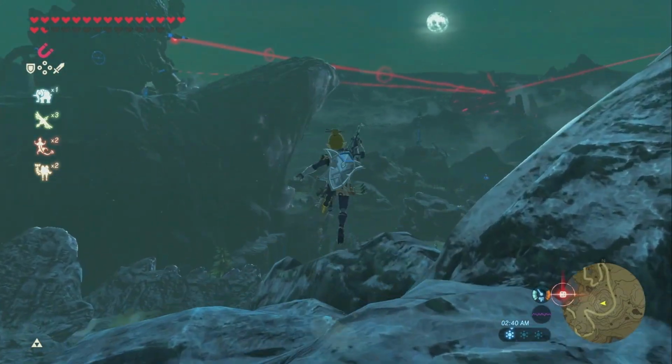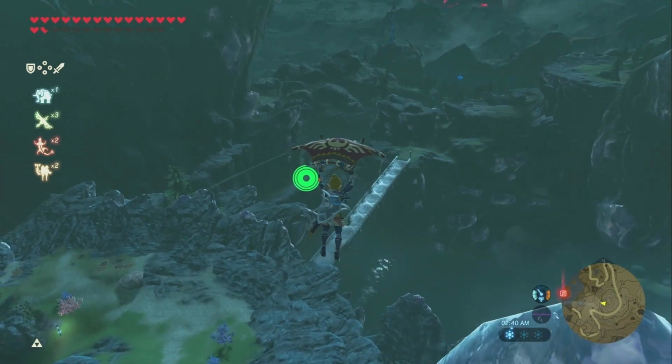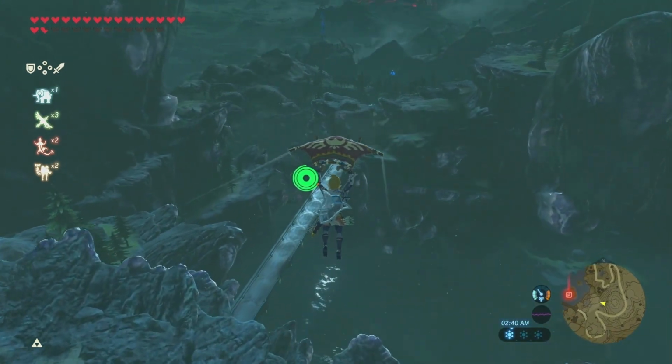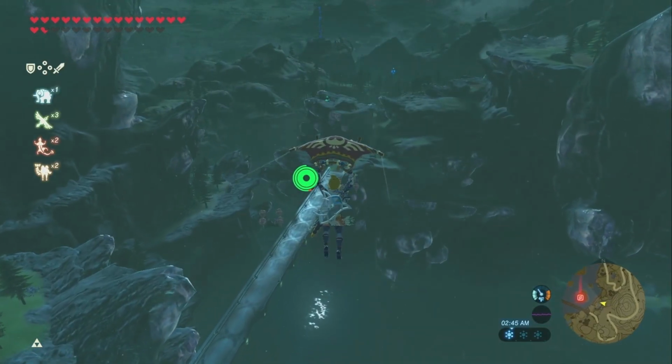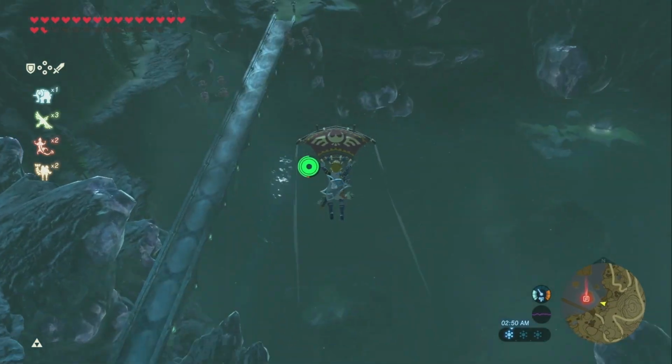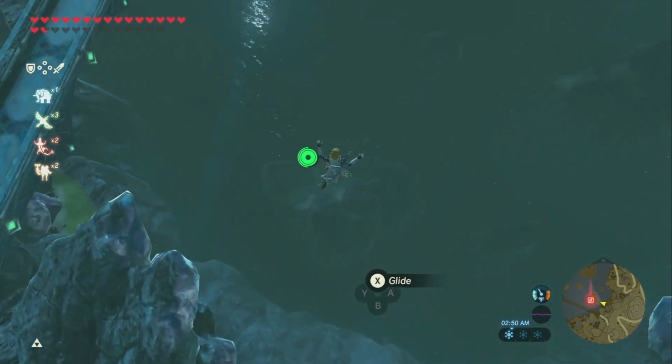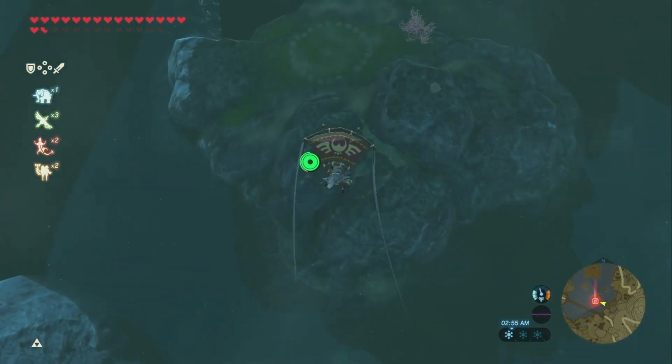Get rid of the chimney. A common approach is to replace the water heater with a sidewall vented unit. Power vented or fan-assisted water heaters can be vented through the sidewall using ABS or PVC piping typically.